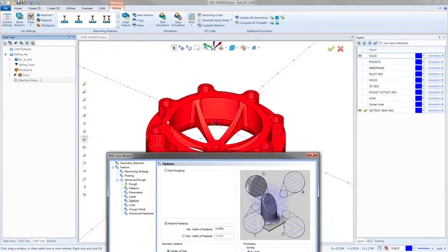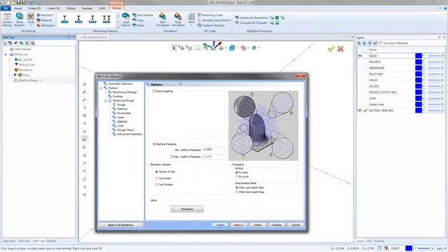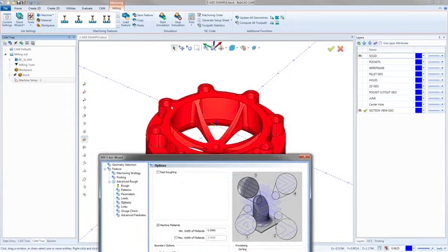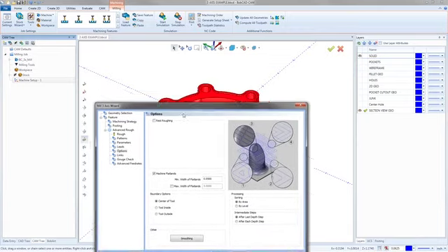So if this is what we'll call top of part, this is a 50 thou drop from here down to this floor. I'm doing a 1/4 inch depth of cut. So my first pass is going to be way down here, before it's not even going to see this area. It's going to be way down here. So machine flatlands would recognize that there's this area that's in between our depth of cut. It doesn't happen to hit perfectly on our depth of cut, and so it's not going to cut that normally.